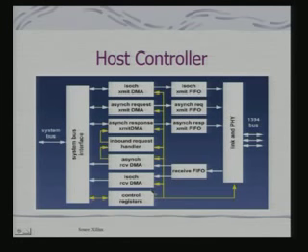Now, here you will find that for different kinds of data, different DMA channels have been identified, and the inbound request handler is different from the other transmit handlers, because these DMA channels have to be configured and handled differently depending on how the data is mapped onto the memory for subsequent usage.